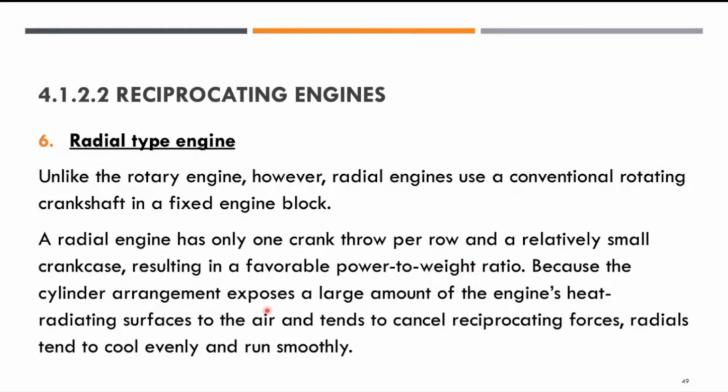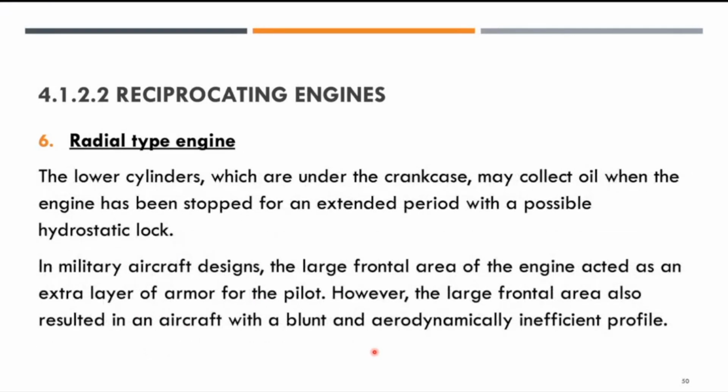Because the cylinder arrangement exposes a large amount of the engine's heat radiating surfaces to the air and tends to cancel reciprocating forces, radials tend to cool evenly and run smoothly. However, the lower cylinders under the crankcase may collect oil when the engine has stopped for an extended period, with a possible hydrostatic lock.